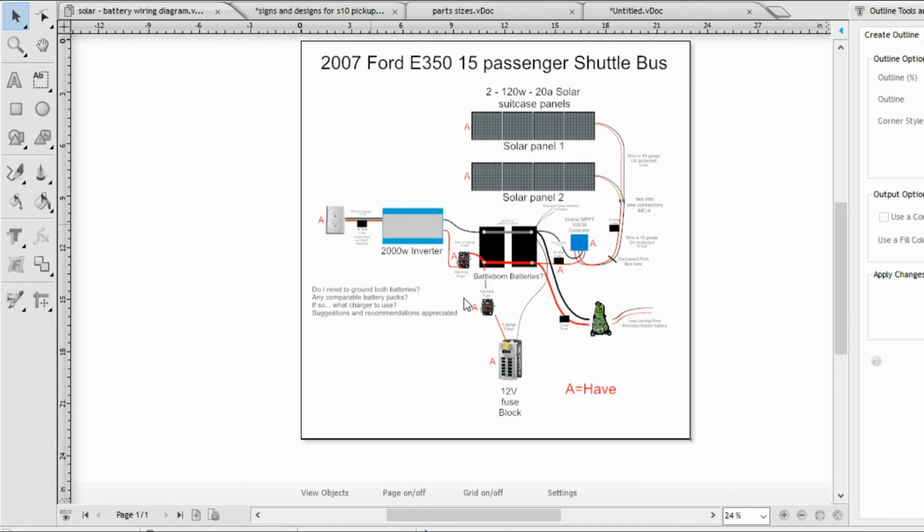And this one right here will be coming out and going to the 110 side. I have a t-shirt machine that draws 9.7 amps and it's 1650 watts. So this converter is just about the minimal I'll need for it.